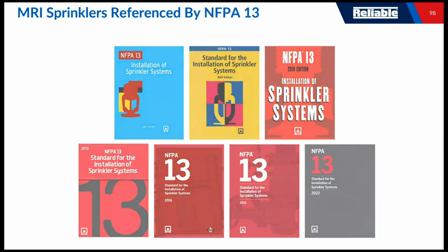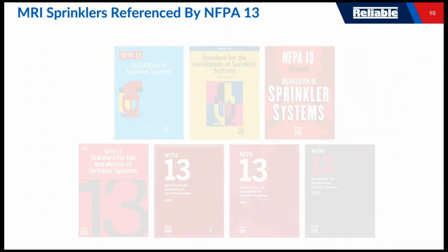So are MRI sprinklers referenced by NFPA 13? No, you won't find any real guidance on an MRI on what to do with it. This is really about opting for creating that product or for opting for using that product because it's just the right thing to do. It's a better thing. It goes along the same lines of, hey, you don't have to use a pre-action system in an MRI space, but a lot of times you do because you want to have a better premium sprinkler system and products because that machine is millions of dollars. So you will not find anything in NFPA 13 about that.